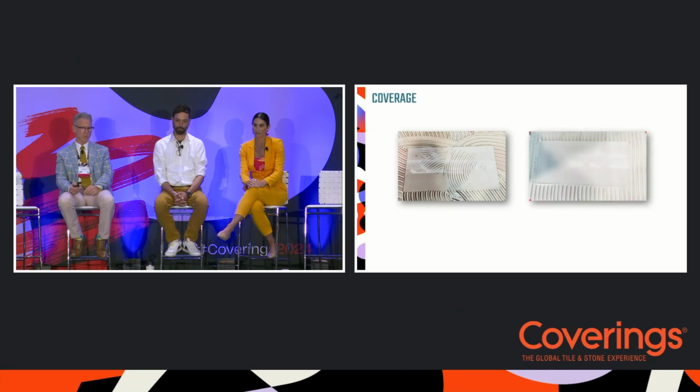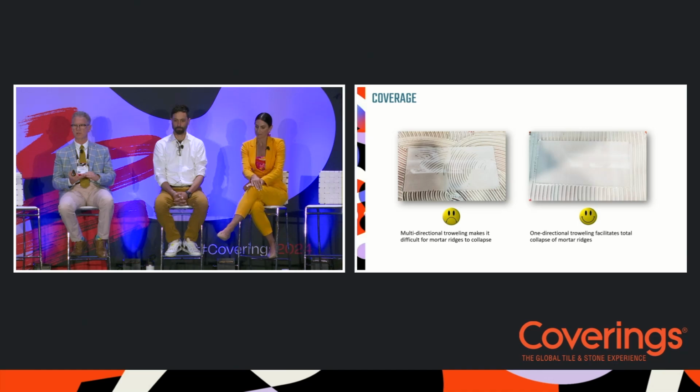Now this slide will clarify what I mean by embedment. There's plenty of mortar in each of these examples, but it was troweled differently. So the example on the left, the mortar was troweled on in all different directions, and this is a piece of clear plexiglass that we're just using in lieu of the tile so we can see what's happening. We use this as a training exercise in our training center so that the apprentices can see what we want to have, and in the example on the right, we want those ridges of mortar between the valleys to collapse into the valleys so that all that mortar just smushes, to use a technical term, smushes down, and that tile literally gets sucked in, all right? And that cannot happen physically if you're troweling in multiple directions.